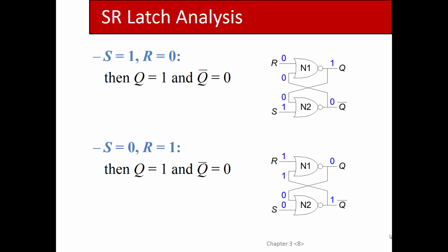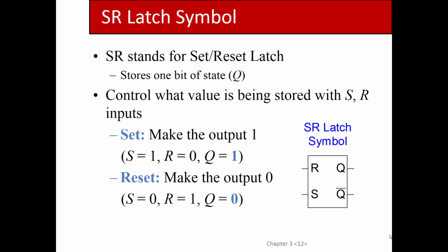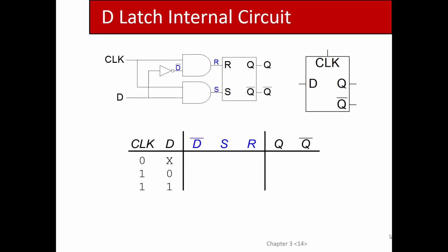Okay, so another thing you can do is take an RS latch, and you can put these two AND gates here that basically just enforce the rule. But the way you do it is you have a clock, which is one of the inputs on both these AND gates.